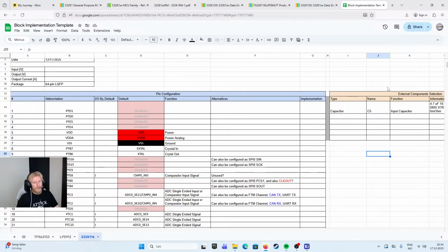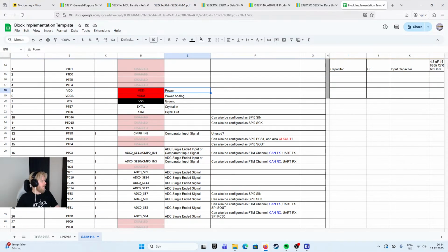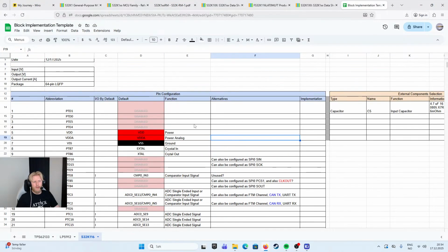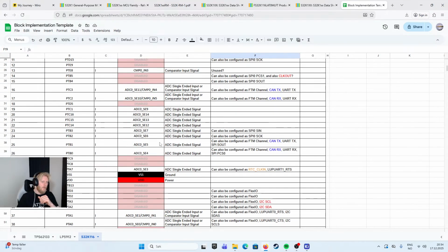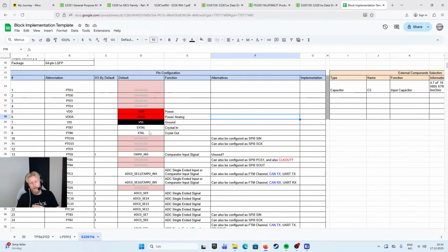We might have to break this up into modules. So all of these are connected to some modules. For example, power, I guess it's the power management or something, or system block. So maybe everything revolving around power we connect together, like decoupling, for example, bulk capacitors, crystal together, selecting load capacitance.